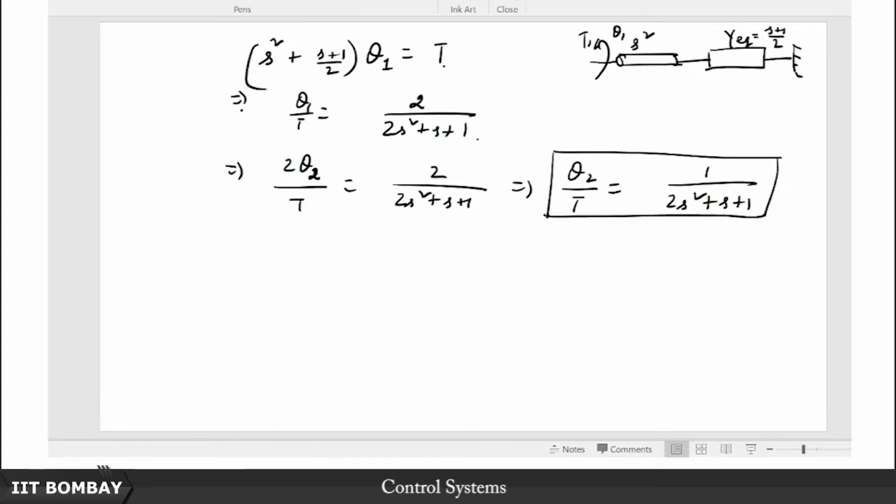So I want you to notice and take home from this discussion the point that there is a very strong analogy between the analysis of electrical circuits and those of these rotational systems. Of course, barring few exceptions like I pointed out in the previous lecture, there are these things called inerters, which are in the true sense the equivalents of inductors. So every mechanical system, be it rotational or translational, can be depicted by an equivalent electrical circuit, but not every electrical circuit can be always depicted by an equivalent mechanical system, because things like masses and inertia blocks are like single terminal devices. In other words, you cannot share mass between two loops, two independent loops all the time.